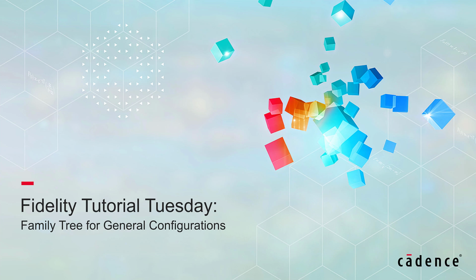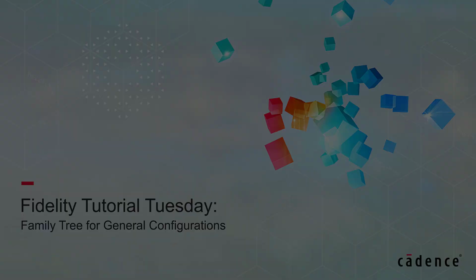Today, I will show you how to use the family tree for general configurations and demonstrate why it can be a time saver in your workflow. The family tree allows you to create a template with an assembly structure for each family of similar geometries. It is convenient to use a family tree in case you need to swap geometry pieces to investigate multiple designs. As we will see in a minute, the family tree allows for a quick change in geometry without having to change the mesh or computation settings.